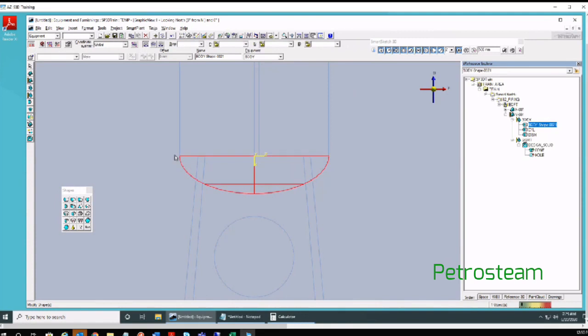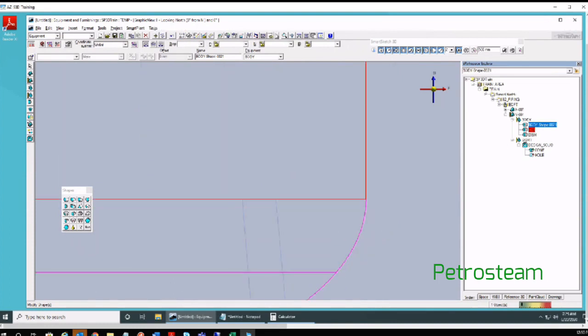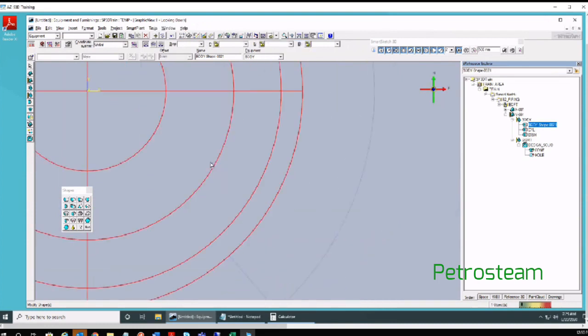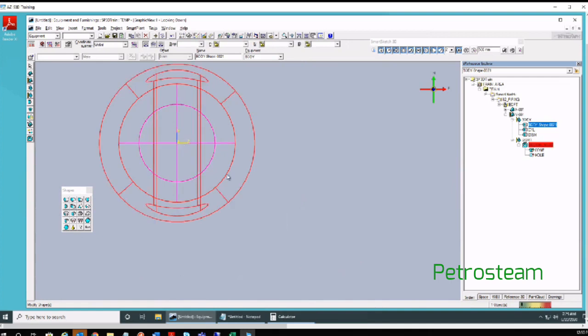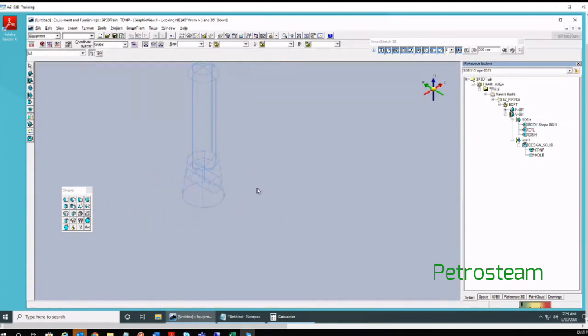In the wireframe mode, I can see that it is coming correctly here. If you zoom, you can just see. I will verify in the top view also whether it's coming correctly. Okay, it's exactly matching with my cylinder. Now I will just accept this location as it is.